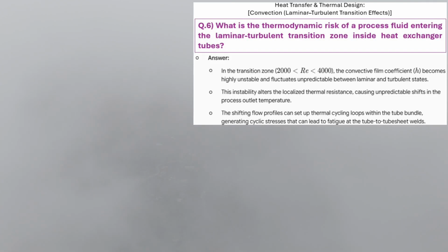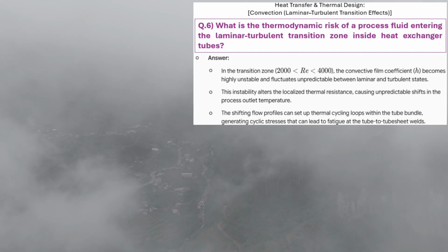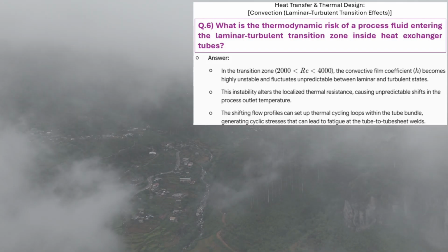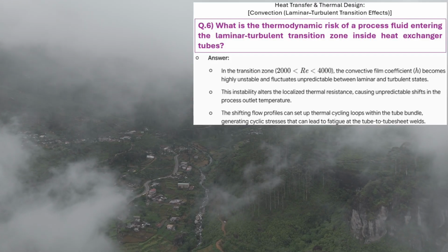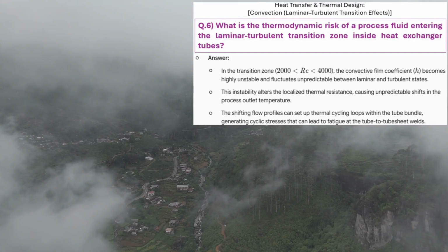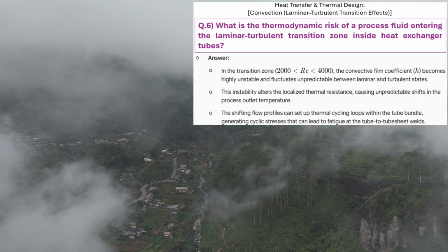and U-bend radiuses. And the trap is assuming an average heat transfer coefficient will keep performance stable during turndown. Which is a deeply flawed, naive assumption. The fluid mechanics do not average out. It causes downstream columns to hunt continuously, perpetually opening and closing valves. Provide the operational metrics of this failure so the observers understand the scale.